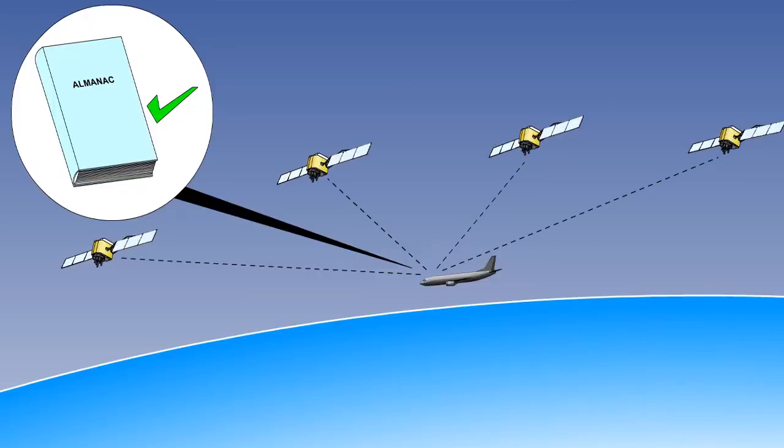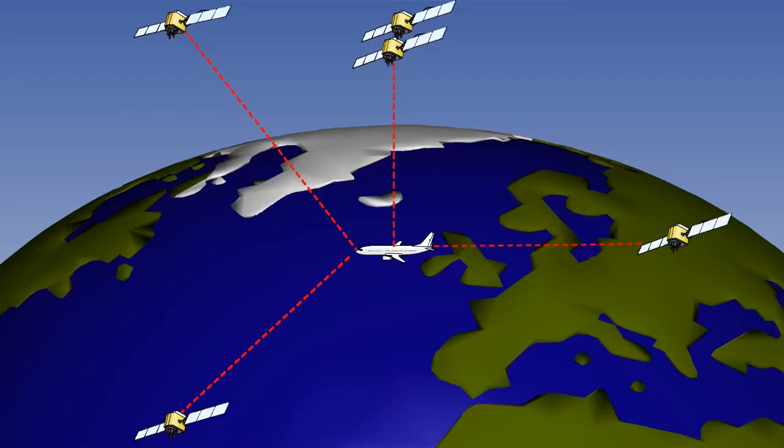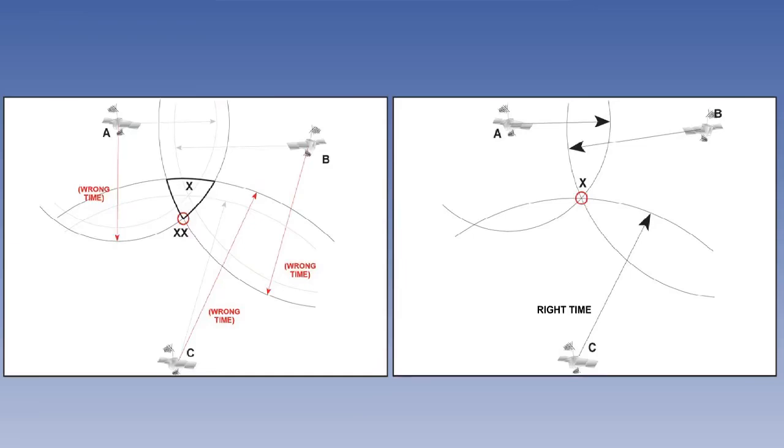After the navigation message almanac data has been downloaded, the receiver checks all satellites to determine the best available for use. The best fix from 4 satellites is with 3 close to the horizon and 1 directly overhead. Initial pseudo-ranges may be in error because of receiver clock inaccuracy.